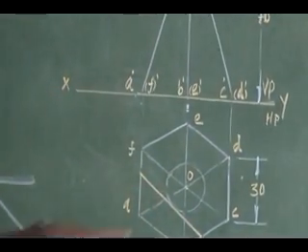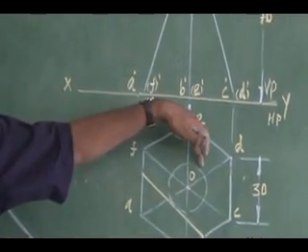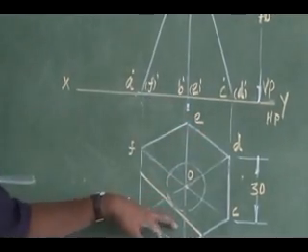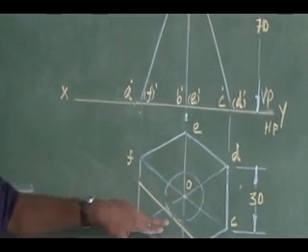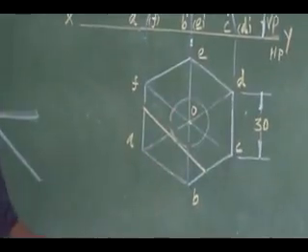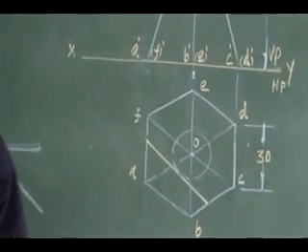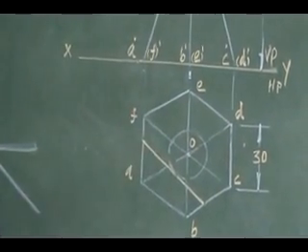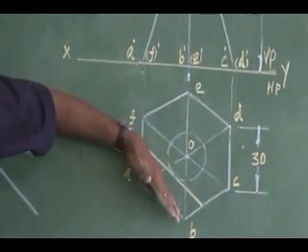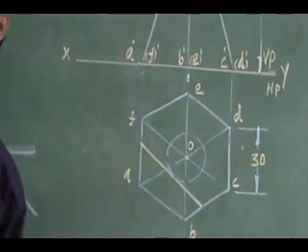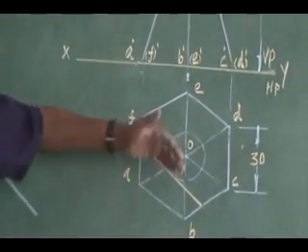You can ask why I have taken the tangent on the outside. It can be tangent the other way, right? So I have the 40 degree inclination at two locations where I can have my cutting plane. Why have I drawn it here? The smaller portion is what I am looking at in the sectional view. Whatever portion you are sectioning and removing for viewing the section, the smaller portion, will be removed. So this is the smaller portion I am removing.